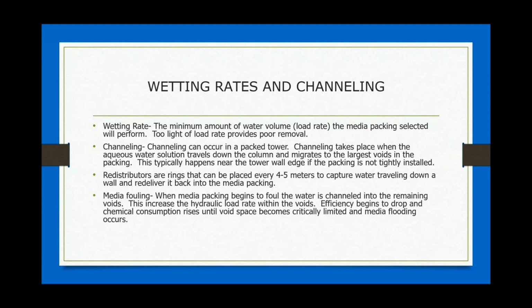Media fouling: when media packing begins to foul, the water is channeled into the remaining voids. So this increases the hydraulic load rate within the voids. The efficiency begins to drop, and the chemical consumption rises post-degasification, until the void spaces become critically limited and media flooding occurs. So as the fouling gets severe enough, then water will not travel through the media and the tower will flood.